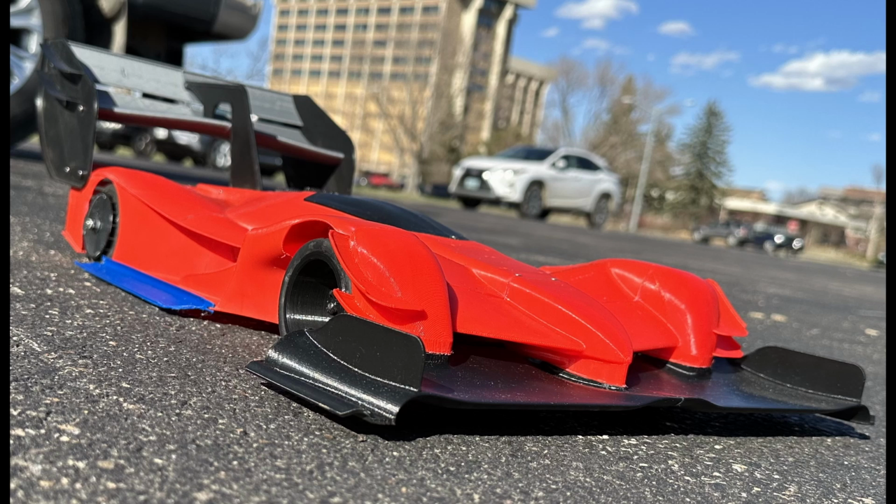Also, contrary to internet folklore, downforce to tractive force is not a linear relationship due to tire deformation, particularly RC car tires, which are not pneumatic tires. So based on the initial testing, the RC Hypercar needs to generate roughly 2.5 to 3 times its weight in downforce, or roughly 14 pounds or 6.4 kilograms, to reach that goal of 3 lateral Gs.